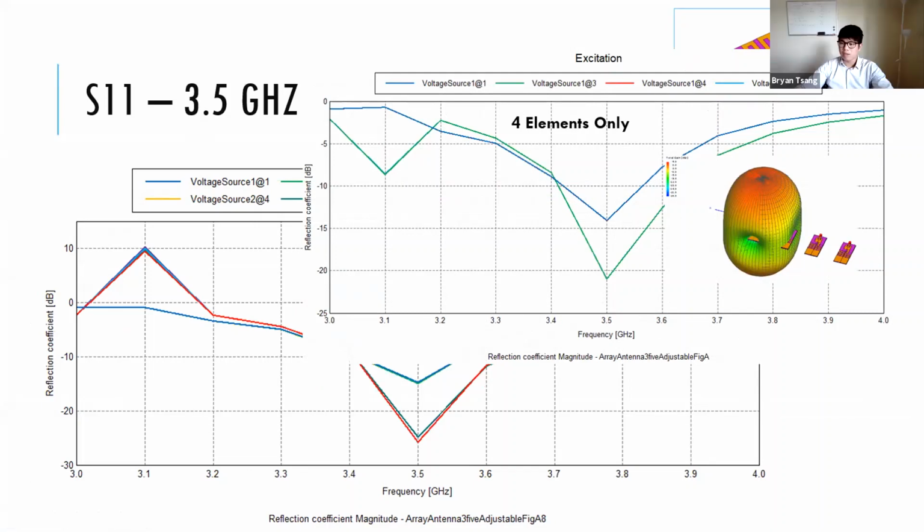The hunch that I have is that you have coupling between them, and somehow it managed to believe that when it puts in a certain amount of power to all of them, it gets more power out at 3 of them than the other one. But it's weird because they're 10 dB higher and one of them is 3 dB down. My best guess is that you have coupling between them, which is causing it to look that way, but that shouldn't really happen. I'm not sure where that.